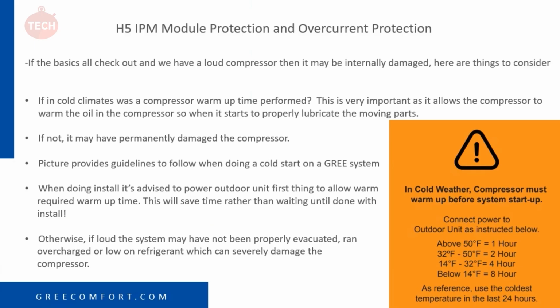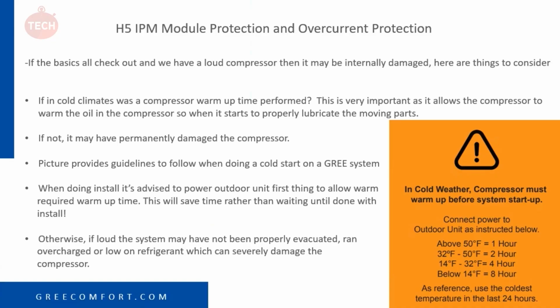Otherwise, if loud, the system may not have been properly evacuated, ran overcharged, or low refrigerant, which can severely damage the compressor as well. So if everything checks out, we went through the list and that compressor is still loud and we didn't do a cold start on it, it may be something as simple as the unit ran overcharged, undercharged, or with a dirty condenser for a long period of time and caused damage to that compressor.